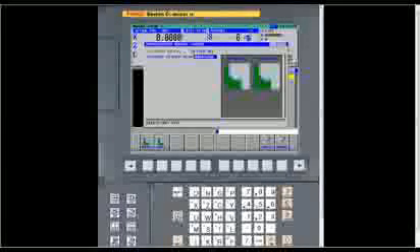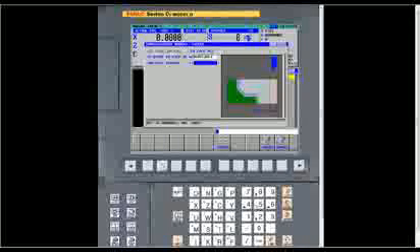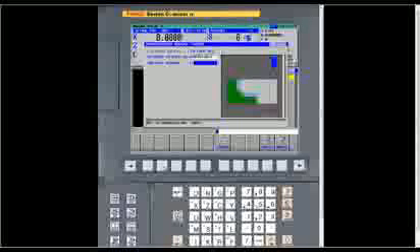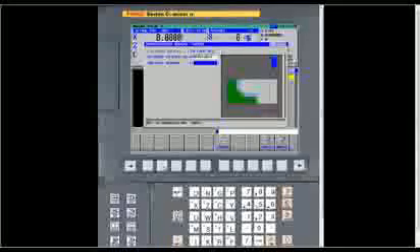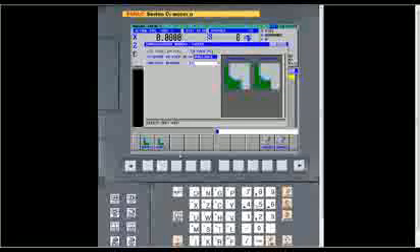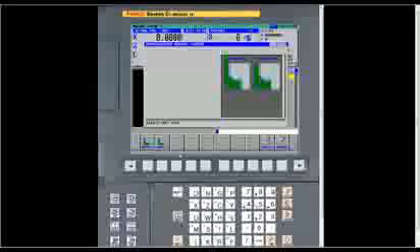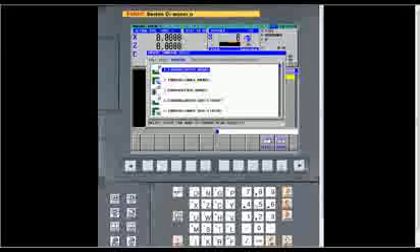And then also within turning, this is a very nice feature. If you're running chucker work, where you have clearance at the end of the part, you can tell it to face the end of the part. You do not have to make a separate facing cycle. You can do it all within the turning rough. But as a note of caution here, you have to make sure that you're not using a center in the end of the part, because it's going to face all the way down to X0. So you have to have clearance to where you can get to the end of the part all the way down to the center. So that's all the different fields within a rough turning cycle. As I said, what's good about all these? They're very similar. This looks just like the drill cycle. Just fill in the blanks. Then we cancel out of that. We go back into our turning cycles.